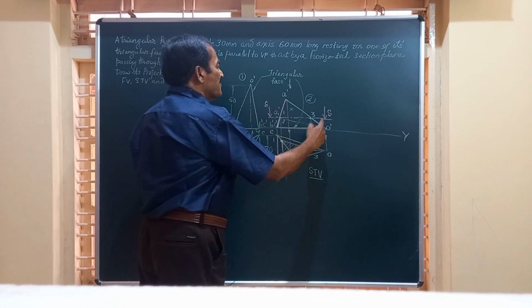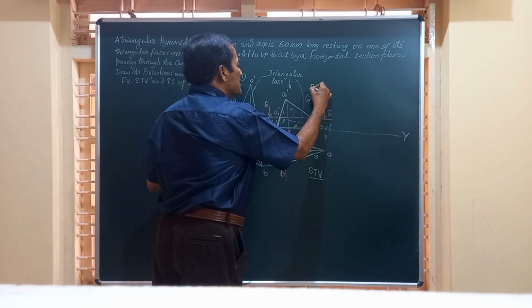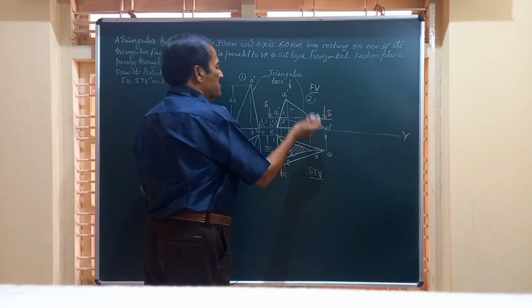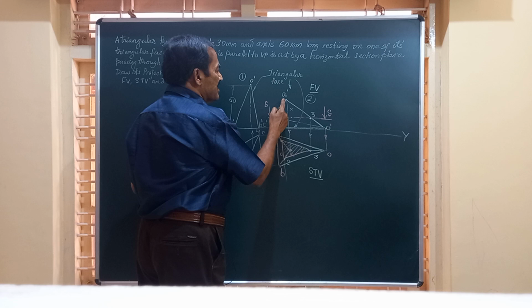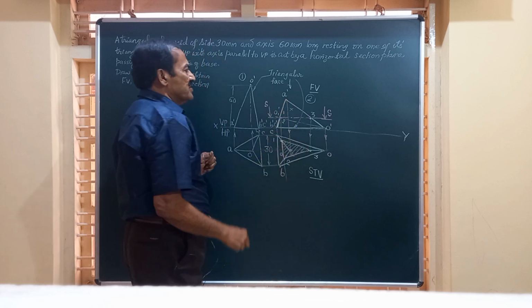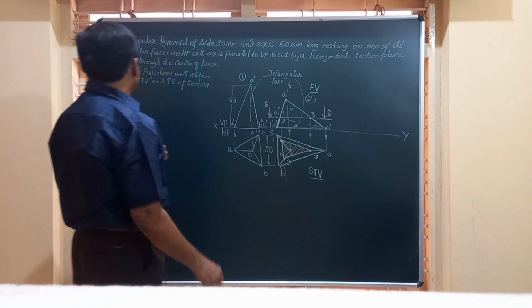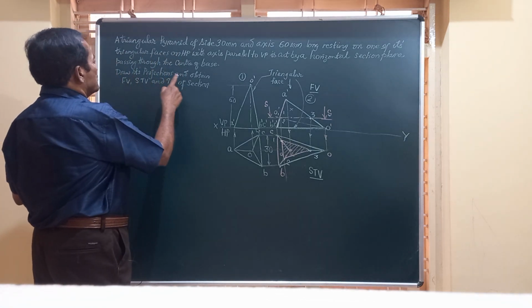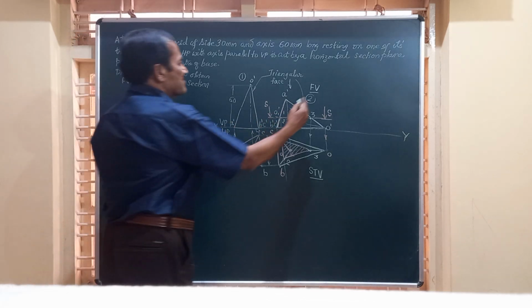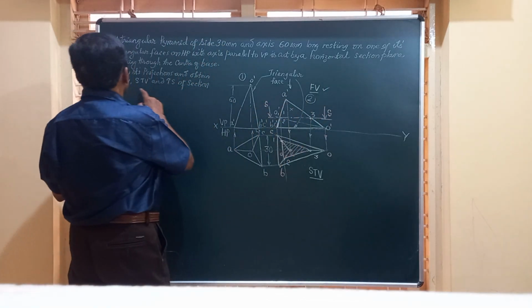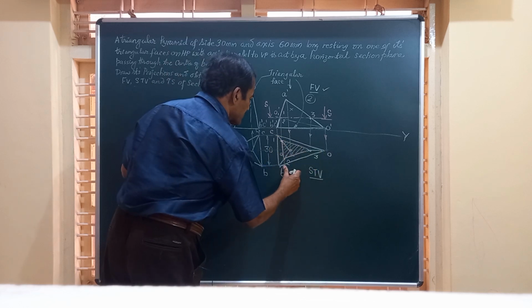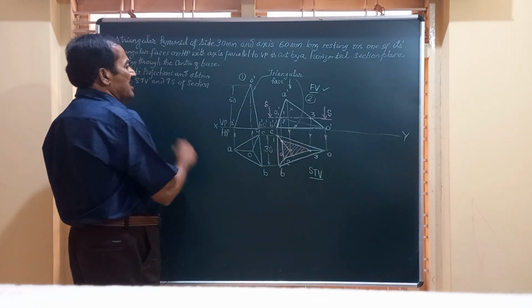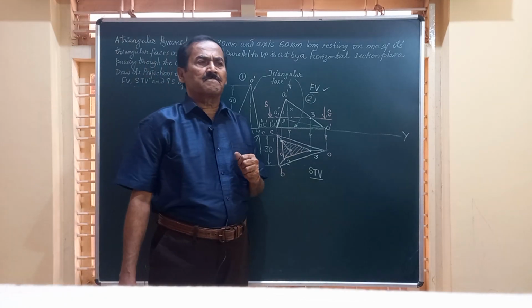And this figure in the front view, it represents the front view which is marked above the XY line, and the portion above this 3 and above this point are to be shown by thin lines, just visible lines. You can show them by thin lines. Friends, what is being asked is to draw its projection and obtain the front view. Yes, front view we have got here. The sectional top view, the complete figure here, is called the sectional top view STV, and true shape of the section.